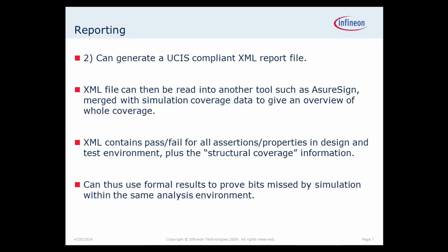We can then link it with coverage data from other tooling. So on this particular block I'm working on now, we are running properties to probably test 80 to 90% of the block, but due to the state depth of the design, it's very difficult to fully formally verify it over all cases. So we're also running it with random test messages, but the problem then comes is how do you avoid verifying the same thing twice?